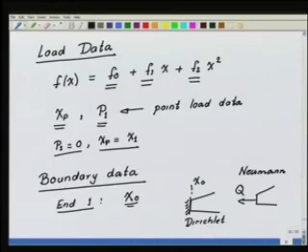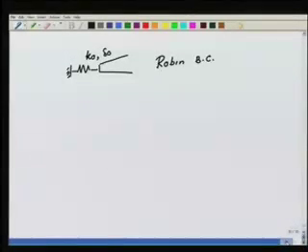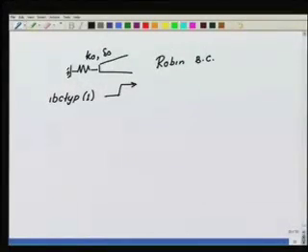So we have to have the feature that at this end I should be able to give any one of these boundary conditions, and along with the boundary condition type I should be able to input the data that goes with it. Here, Dirichlet means U0 is given as U0 bar. So let us say that we will specify the boundary condition type at N1 by the following numbers.